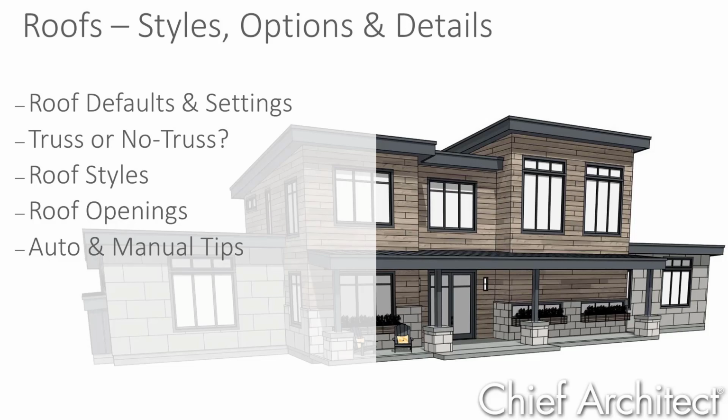If you have a complicated roof, you may need to manually change the roof, and I'll briefly touch on manual roofs. For this project, I'll place roof openings to expose the patio and add some skylights. Let's get started with the automatic roof tool.